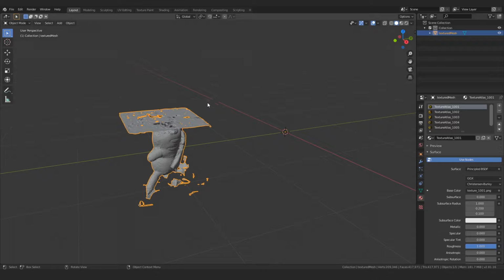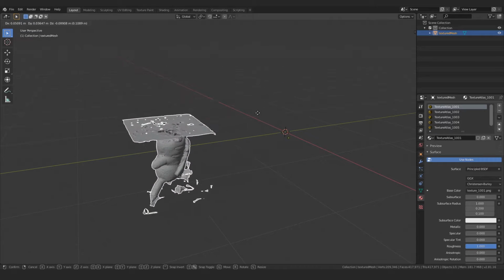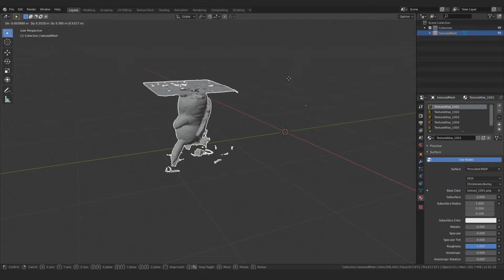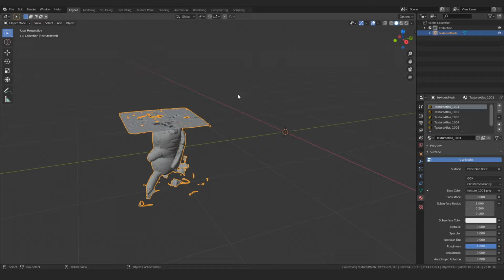We can rotate it, which is exactly what it sounds like, and then we can scale it, which is kind of like making it larger or smaller, essentially. Any of those transformations, which we might do on this object, are going to be done in relation to this pivot or origin point. So if I want to move it by hitting the G key, you'll see that that point moves and the Pikachu moves in relation to it. I can cancel this transformation by hitting the right click on my mouse or the escape key on my keyboard.